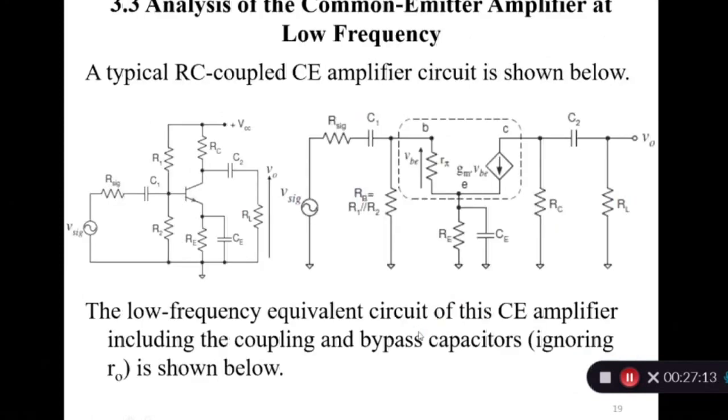Now, the main section of this numerical is the center one. What happens in the center one? We have to see the resistor looking from CE. Short circuit this one, short circuit this one. If you are looking from here is RC. Now you have to decide this R pi parallel or series. Because this R pi is here, is in the circuit, not like a previous one like 1 upon GM, but here R pi.